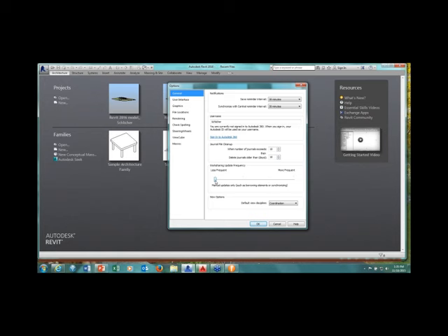What happens when this is to the right, two things really happen. When you go to manipulate an element, if this is all the way to the right-hand side, more frequent, you'll start seeing delays of 5, 6, 7 seconds before Revit allows you to manipulate that object. Also, it's constantly going back to the central file when it's set over here. Moving it, it will only check the central file when we do a sync to central.